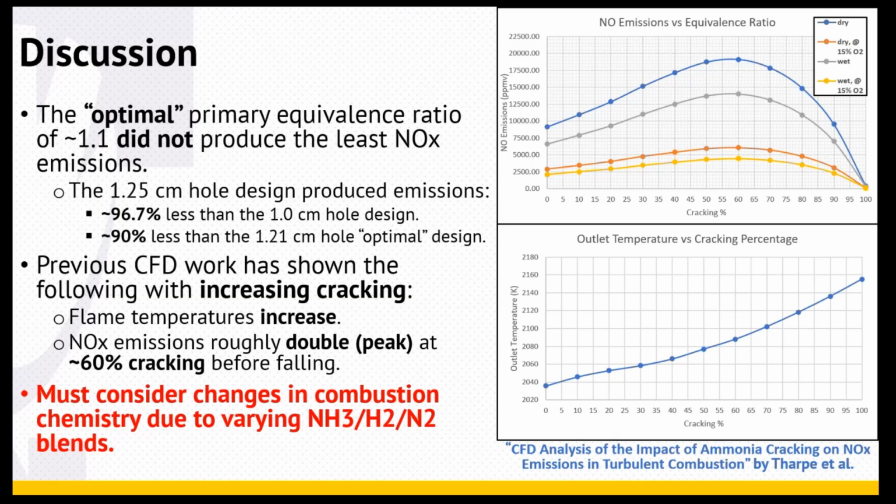And what I believe is going on here is that as the fuel cracks, the flame temperature increases. And because you still have ammonia in that fuel blend, the ammonia is more incentivized at these higher temperatures to react with the oxygen in the air and form NOx molecules.